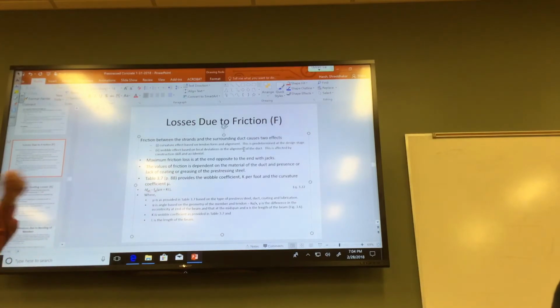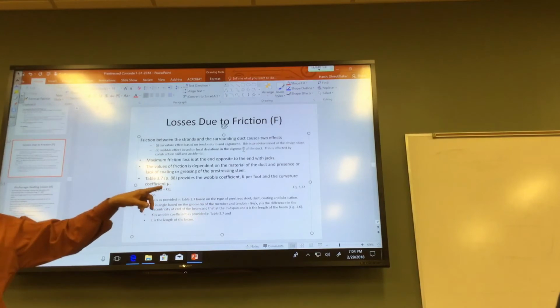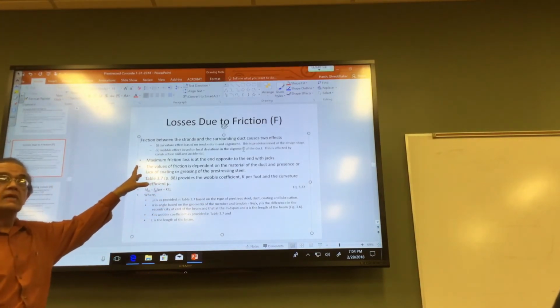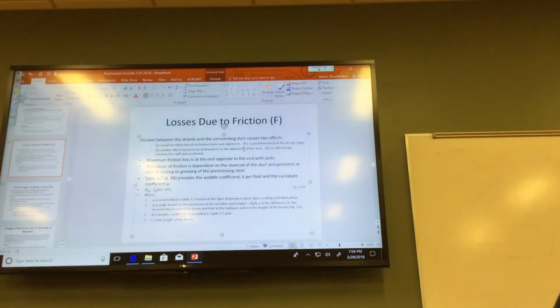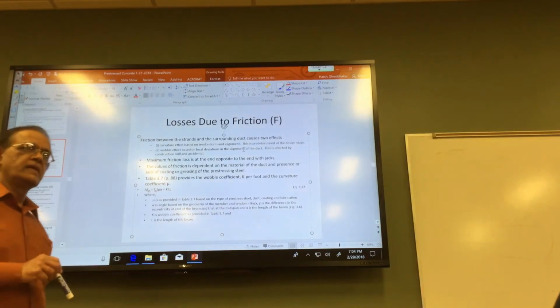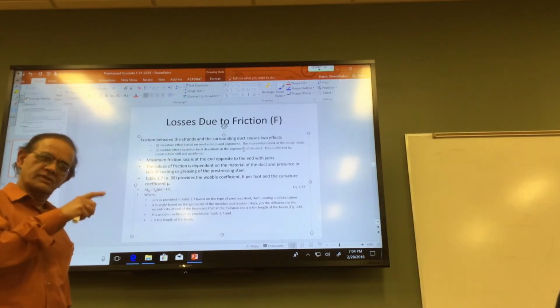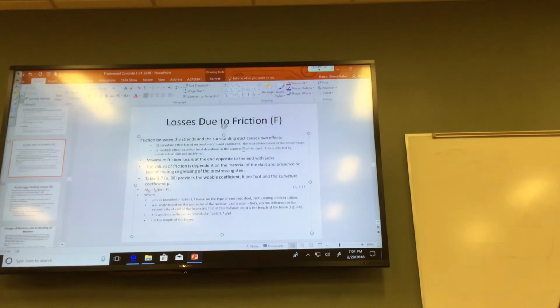And so KL is the other part, which is called the wobble. Right here, as I say on the top, curvature effect based on tendon form and alignment. This is predetermined at the design stage. That means looking at the profile, you can tell what I got. If my profile is straight, then this part is 0. Is the angle in radians or in degrees? Is it a ratio? We'll see. It is closer to a radian, right? It is a ratio. This angle is the perpendicular to the base, tangent, right? That ratio. It's not a real angle. It's a radian, if you will, right?